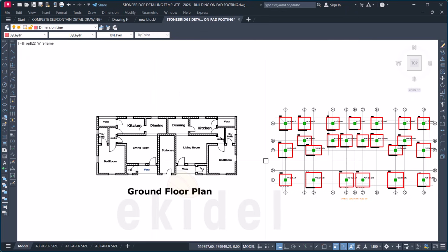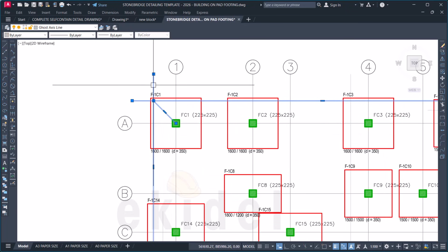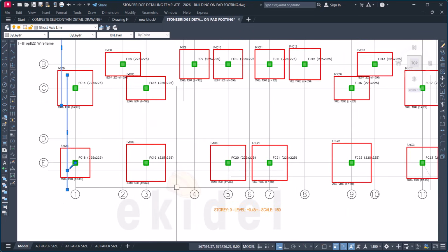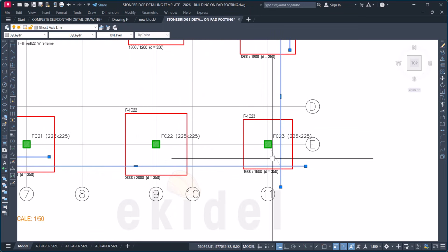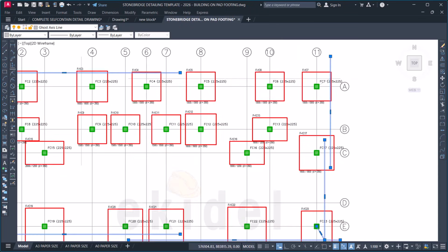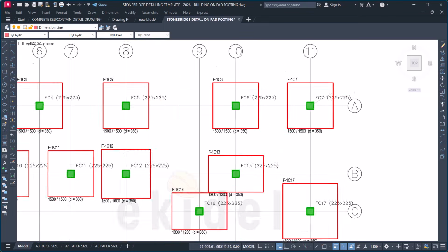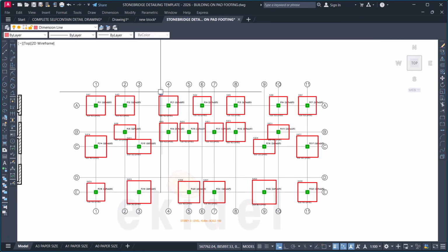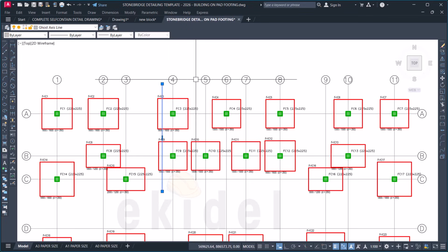Okay, that is fine. So with that now, knowing that all these grid lines too are those cantilever lines that we removed, we will also take them off here from the structural drawing. So I'll take off all these grid lines too. The whole thing is that you are going to remove all the things that are not having direct interface with the ground. So if you have cantilever lines, take them off. This one too is a cantilever line, so I'll remove these two. Okay, that's fine. Then also this one. I will attach this particular drawing file to this video so that you can follow up correctly what we are doing. This is not also among.